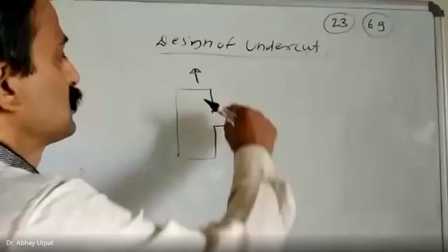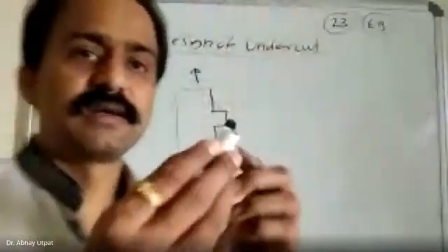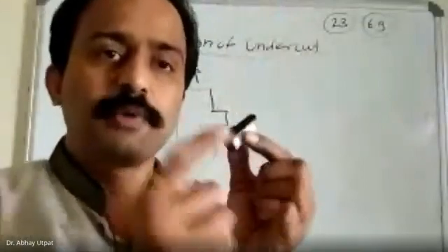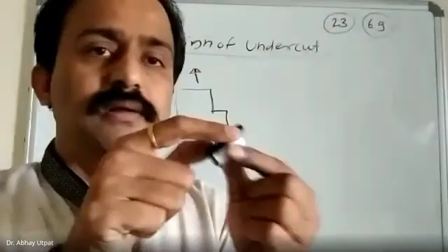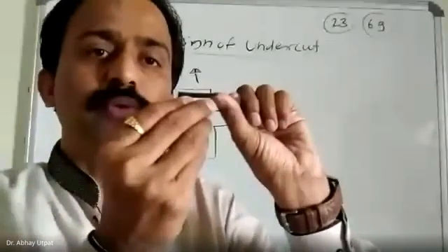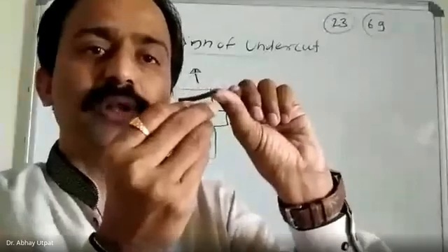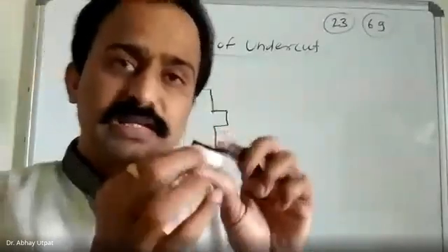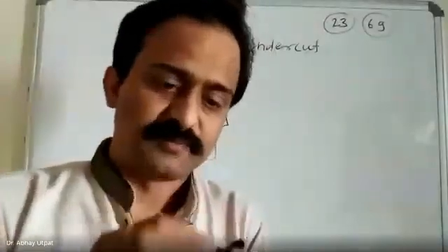Strippable means what? See this. I hope you are observing this, which is used for putting or locking in the pocket. So now this is strippable. Strippable means you can strip it in this way just for the purpose of removal. That's why we are providing the interference fits here.